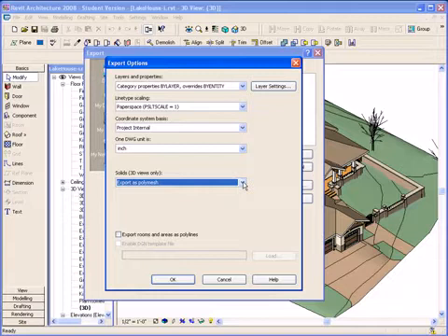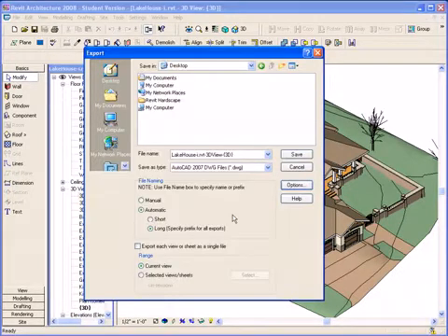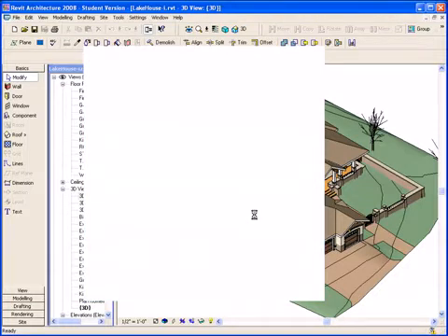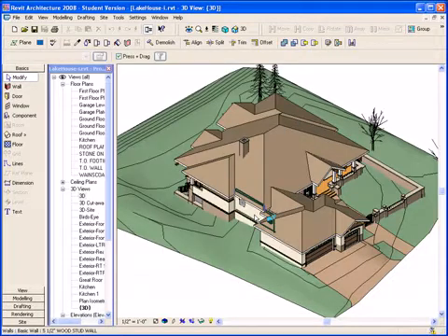Notice the other option, I could export as an ACIS solid. I'm going as a polymesh because I want each surface to be a separate surface so that I can easily put materials on it in Max. If I export it as the ACIS solids, I could then also put materials on them, but I would need multi-sub-object materials. If I needed to do Boolean subtractions to change the geometry, I would have to export it out as a solid. So I've exported that file out and saved it.